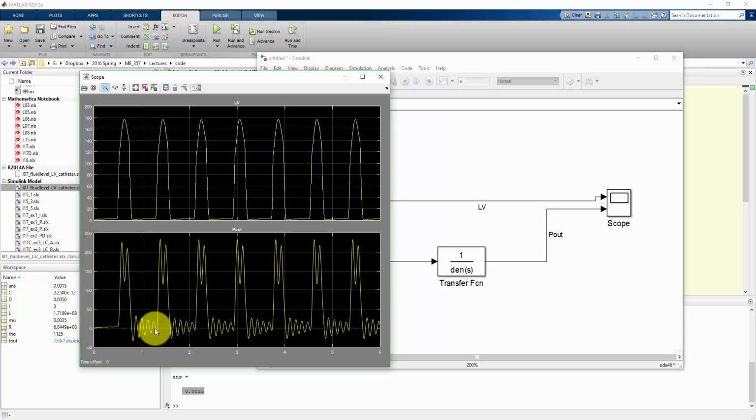What I can do, though, is change the diameter of the catheter and the length of the catheter or tube as well. I'm going to, in this example, leave my pressure sensor alone. Let's just say it's an off-the-shelf piece, and I can't adjust that, but I can adjust the type of tube I'm using that goes to the pressure sensor.